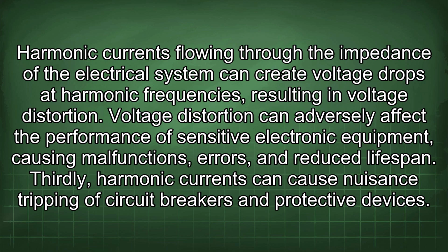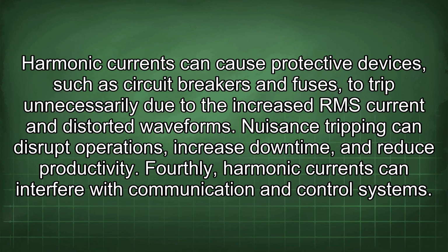Thirdly, harmonic currents can cause nuisance tripping of circuit breakers and protective devices. Harmonic currents can cause protective devices, such as circuit breakers and fuses, to trip unnecessarily due to the increased RMS current and distorted waveforms. Nuisance tripping can disrupt operations, increase downtime, and reduce productivity.